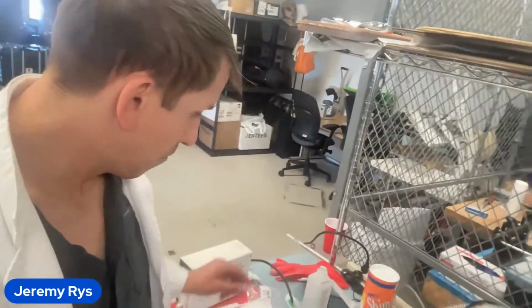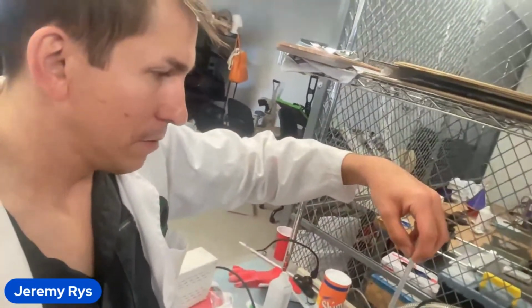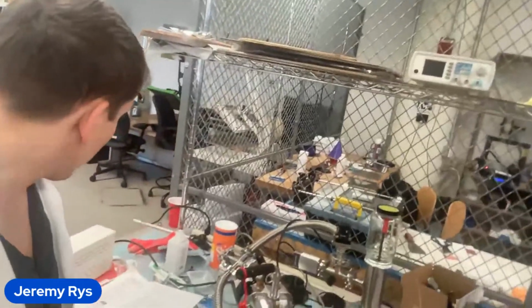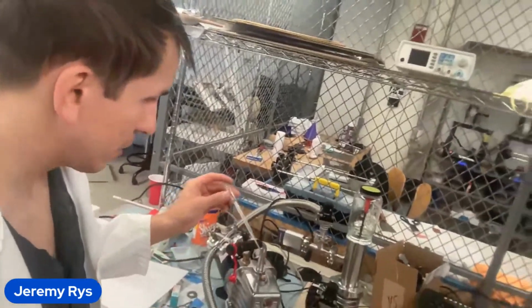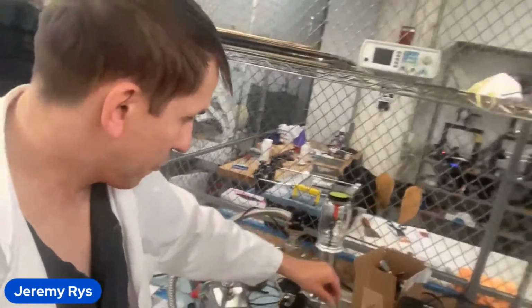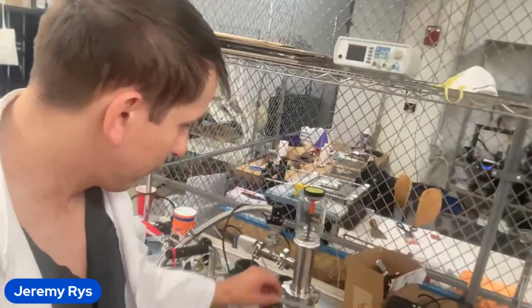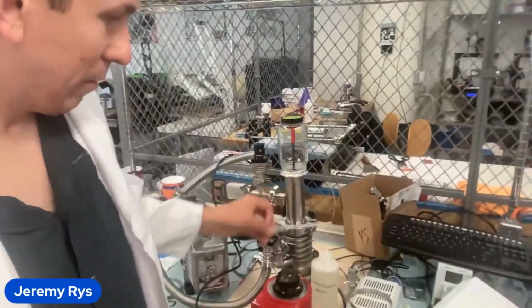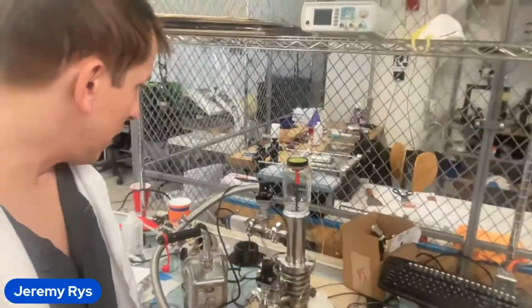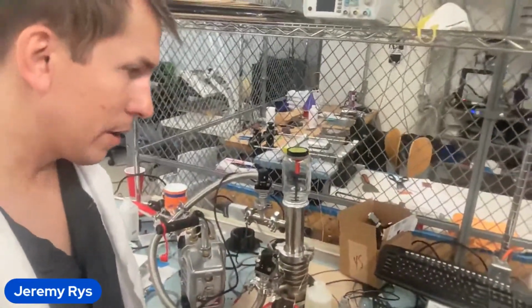So that's 10 of these pipettes filled up to the 3 milliliter line. I don't know where all the measuring tools are, but that's the best way I can do it. So I'm going to use this to measure out 30 cc's of our vacuum pump oil to load up our vacuum pump.